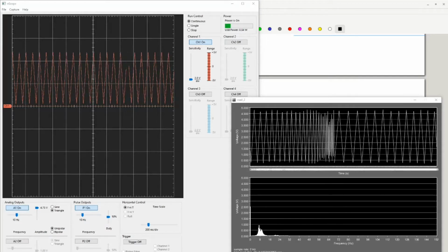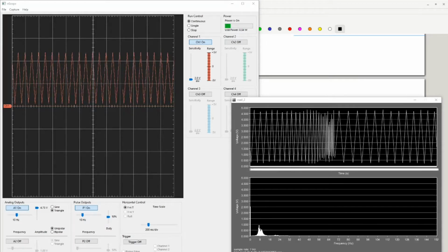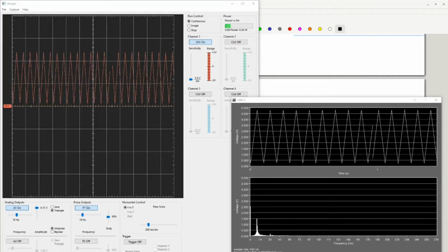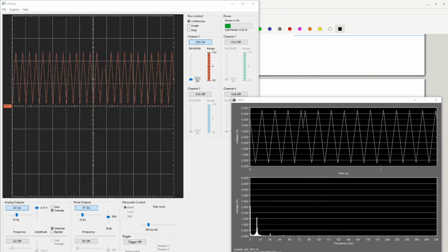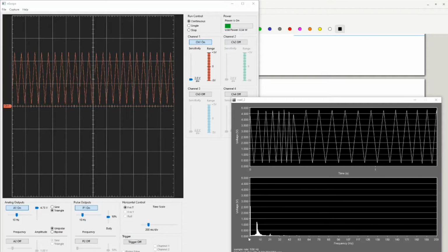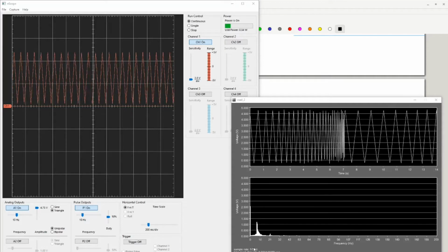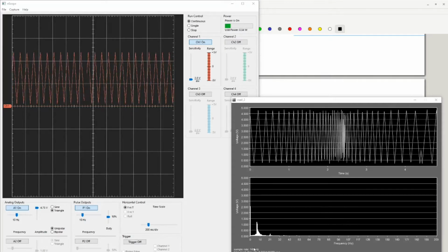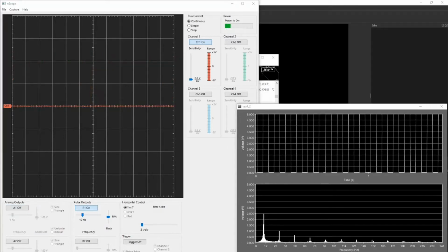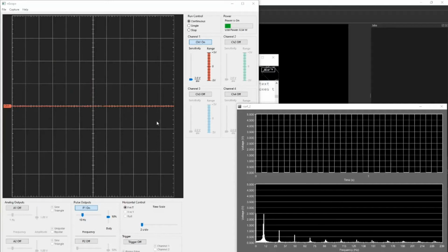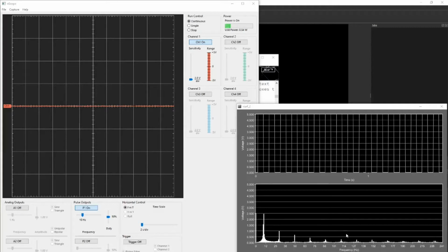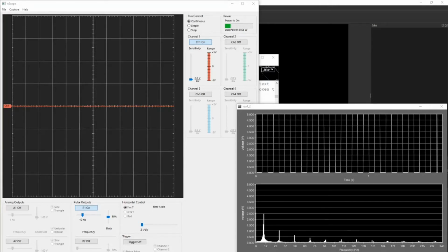I can go down to a sample rate of just 1 Hertz and go up to a sample rate of 600 Hertz, although it's trivial to change in my code, which I will show you later, what the maximum sample rate is. As you can see, it changes depending on the position of that potentiometer. It's also a completely analog scale, which means I can go anywhere in between. So I can very closely fine tune the frequency to exactly 500 Hertz, as you'll see for the lab. And it's very accurate and very stable. It rarely changes more than about 1 Hertz.